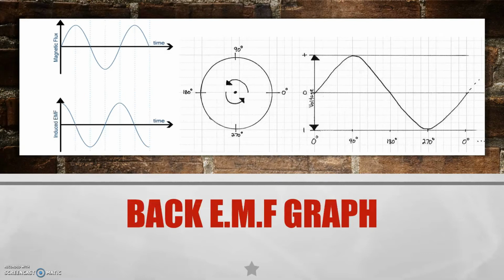Faraday's law states that when the magnetic flux linking a circuit changes, an EMF is induced in the circuit proportional to the rate of change of the flux linkage. As we can see from the graphs, when magnetic flux is zero, EMF and in turn back EMF is at its greatest, and when EMF is at its lowest, aka zero, magnetic flux is at its highest. The voltage and EMF graph has a similar pattern, with the EMF graph being inverse to the voltage graph. However, there's a slight alteration in that the amplitude of the voltage is higher.